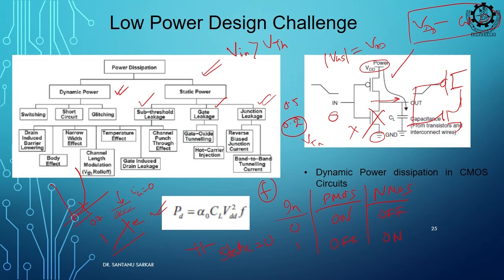Okay. You have to think about how we can stop leakage power, then you will have special design for stopping it. See, first our main importance was static power. Initially we thought that okay, we have moved to CMOS, our problem is gone, static power is 0. Then, as our frequency increased, we have a new problem, that is dynamic power.